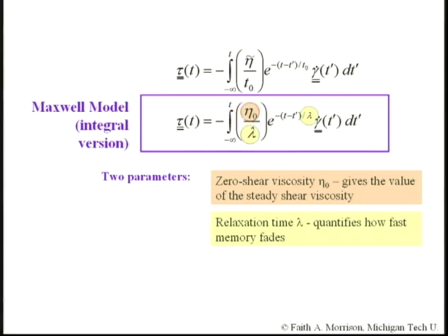Okay? But for our purposes, it's also just a parameter of the model, and it relates to the overall magnitude of the stress. It's a constant. So we've actually very quickly developed a second constitutive equation besides the generalized Newtonian fluid, one that has time dependence, and one that we have to now check out and see how it does.